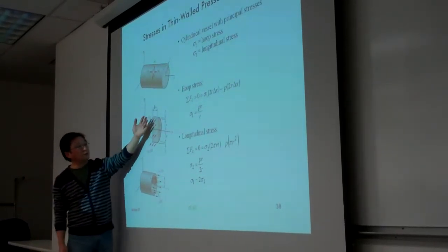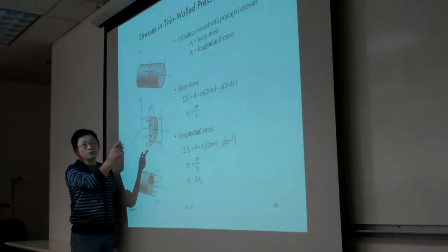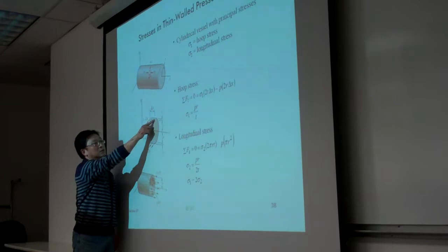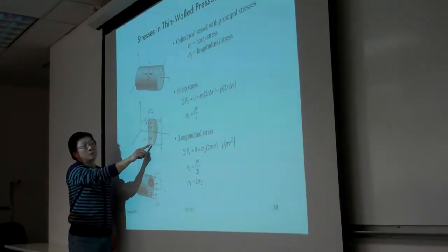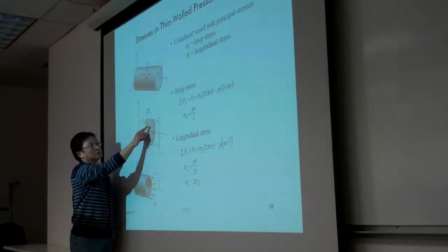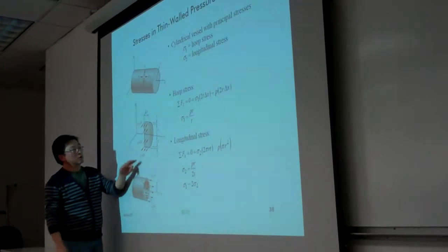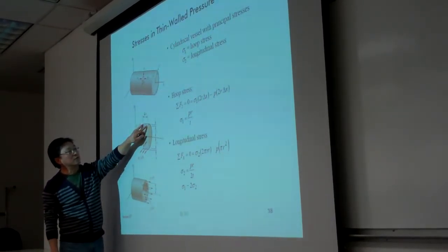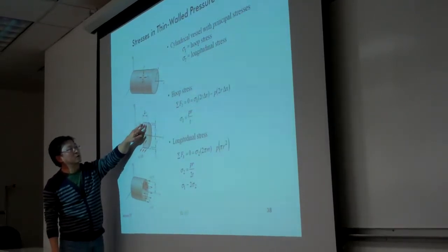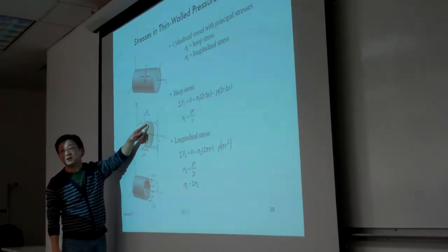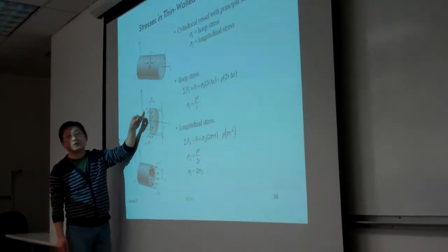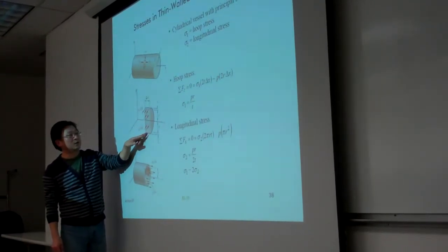So for example, here we take this cut, then we expose the surface of the wall, the top and the bottom. Here we expose the surface of the wall. For each strip of the surface, the area equals delta x multiplied with t, the thickness. So that is the total area that sigma 1 can be applied. The same thing down here.